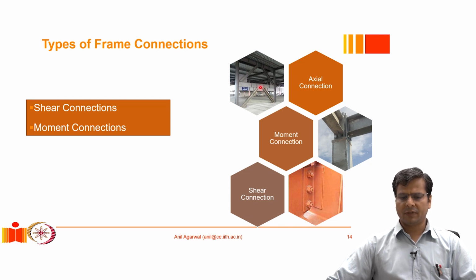In any typical steel building which has some such frames which resist lateral load, such as braced frames and moment resisting frames, the majority of the other frames are typically only frames which are designed to resist only the gravity loads. Such frames typically do not have a very high lateral load resistance, because the design and construction of frames which can resist lateral loads is specialized. It takes a lot of effort, time and cost.